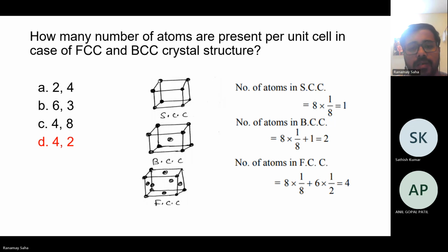In the case of a simple cubic crystal, you have one atom overall, sharing multiple corners. Similarly, an additional atom at the center in case of BCC, and then in FCC, addition of six different atoms on the six faces of this structure, giving additional three atomic contributions.